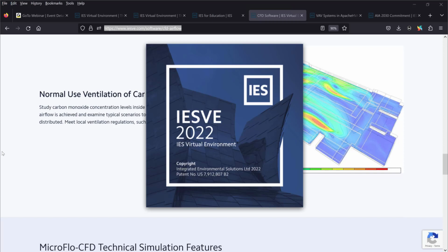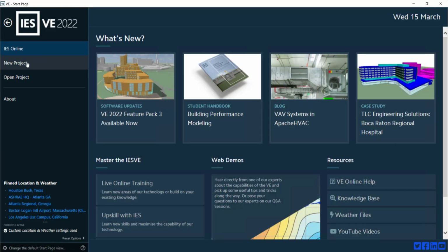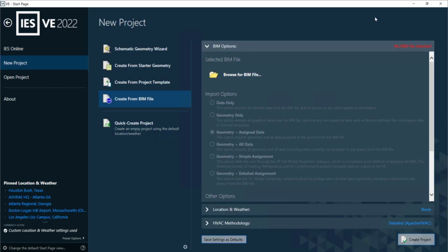Yeah, so it brings all of your geometry. That doesn't just mean your occupied rooms. It also means shades, adjacent buildings. It also brings your site data. So that might be latitude, longitude, weather file. If not, it'll find a weather file for you. Thermodynamically, it will bring materials, all your opaque and glazed construction materials for your model.